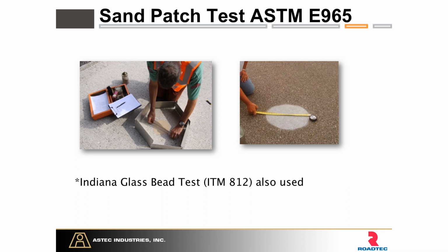So this is one way that has been done in the field, as a field check, because you don't want to require certain drums always. You don't want to force the contractor to buy expensive new equipment, but you also don't want to limit their feet per minute or their forward speed all the time, because that doesn't guarantee a smooth milled surface. This is a nice way to measure in the field and ensure that you can meet a performance spec.